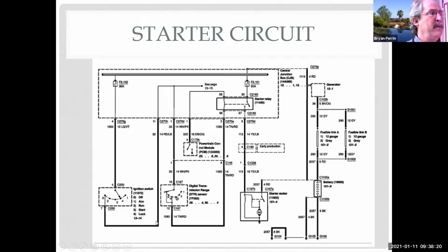Then power would come down through here, and it goes off to another page, but it also comes down to my transmission selector. So I have to be in park or neutral for power to get through the transmission switch. In the old days, you remember you used to be able to start the car in park or start it in gear and it would just lurch forward. And then in the 1970s, they came out with safety switches.